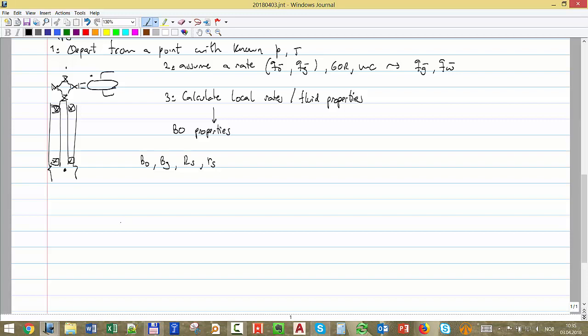Black oil is an approach that we use to say if we have a certain oil and a certain gas at local pressure and temperature, so here we have a volume of gas and a volume of oil. Then I take those volumes through a surface process. It can be any surface process, a sequence of separators, or one single stage straight to standard conditions.